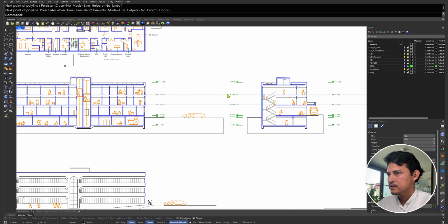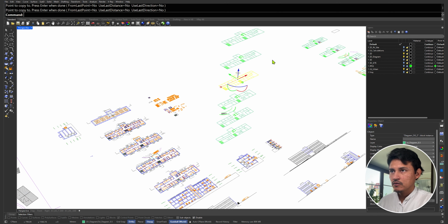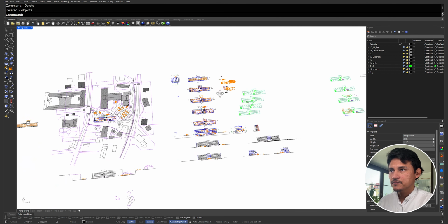And I would also drag lines from the floor plans and use this information for drawing my elevations. The grid could also be extended to the Z direction, and I show you here. I have these 4 drawings, one on top of each other, and there is a distance of 25 meters. So like this, you could make a diagram with the orthogonal projection, and if you want to add more floors, you just copy the next one, always keeping the same distance.